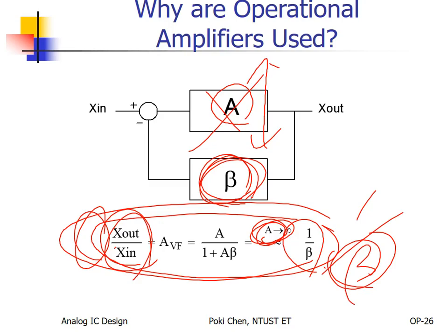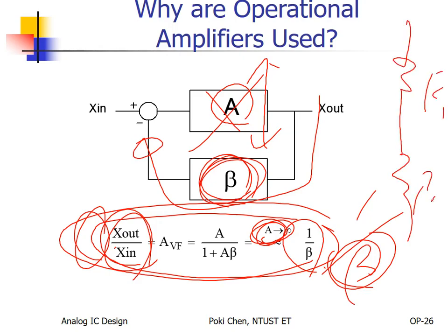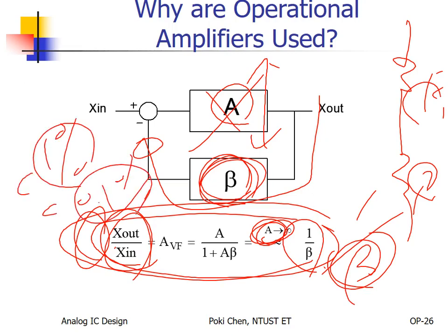Simply because for such kind of feedback network, we apply the same materials, the same kind of devices. For example, R1 and R2. They are of the same type. So if you do good enough layout, common centroid, first order, second order, I don't care, only if you pay enough attention to the layout for the same materials, I promise you, achieving not only 1% or even less, 0.1% accuracy is totally possible.